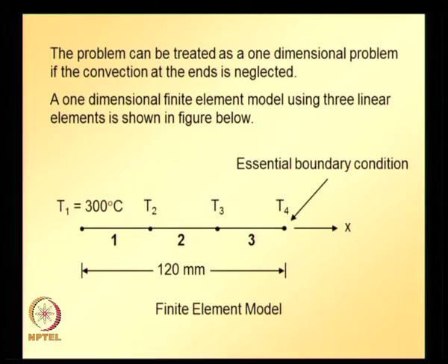Since the material properties like thermal conductivity and convection coefficient, and also the length of each element, are the same, the element equations are going to be identical for all the 3 elements.